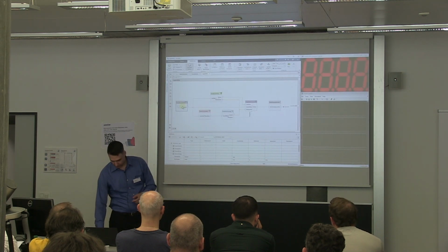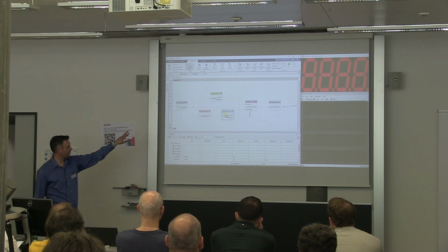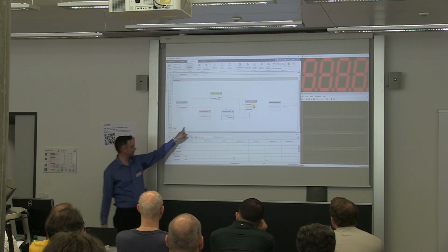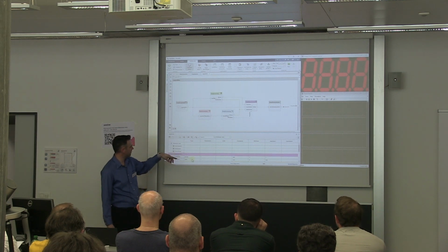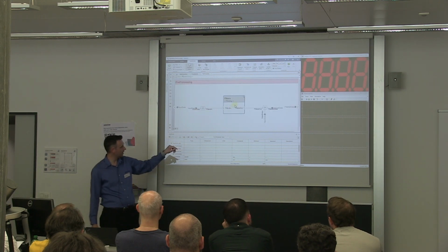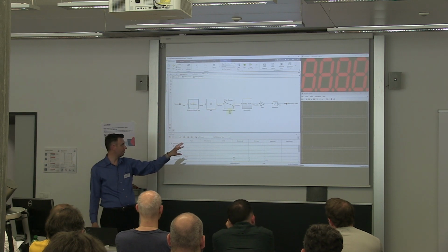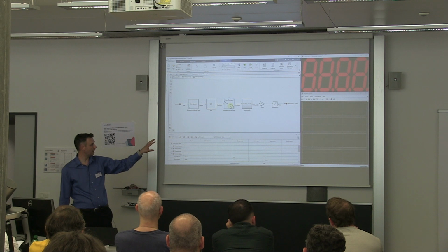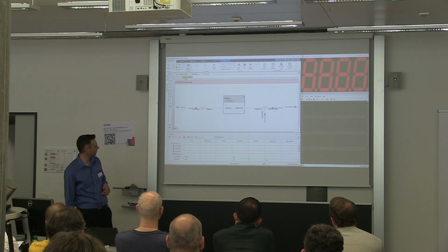Okay. So now I have a video of the system. You can see on the left-hand side we have the data acquisition part, and then we have the signal processing part. And after that we have two components in order to send the data. Here you can see the interface, how the signals are exchanged between the components. And if we go inside one of these components, then we can directly implement them using basic blocks. Okay, that's the idea. So here I have implemented two filters, the bandpass and the low-pass filter.